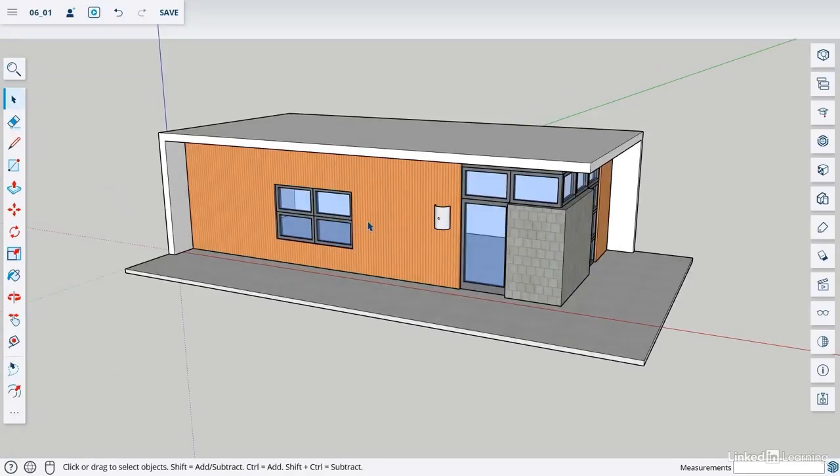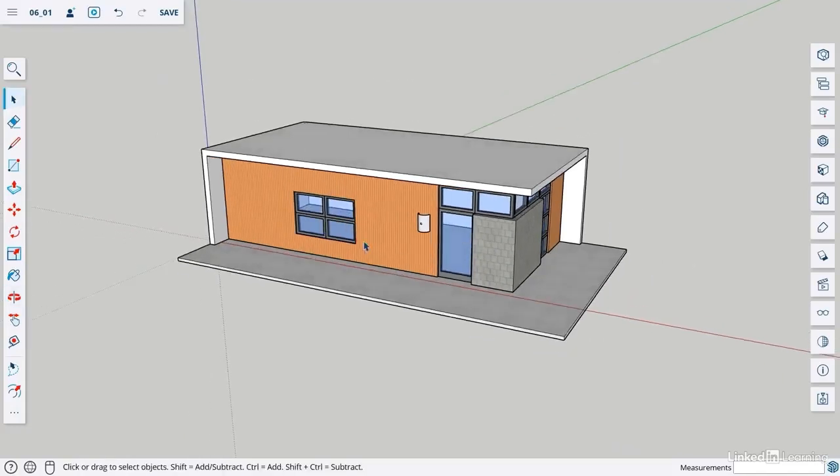Now, the tape measure tool can be used to resize objects in your scene. So if you bring something in and it's not exactly the size you want, you can scale it to a known dimension. I find this is really handy when I bring in things such as floor plans or something like that. I don't really have a specific dimension coming in, but I can force that dimension using the tape measure tool. So let's do this actually fairly simply here. I'm going to go to my tape measure tool, and I'm just going to go from here to here. So that length is 42 feet.